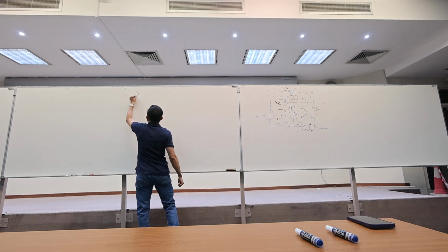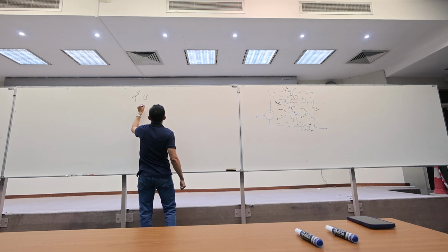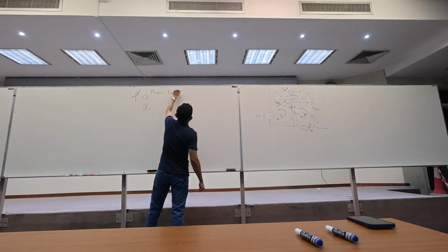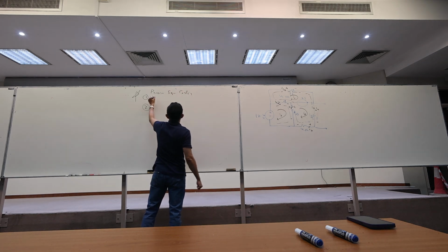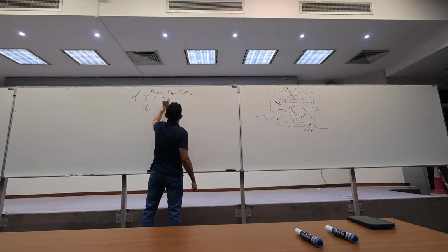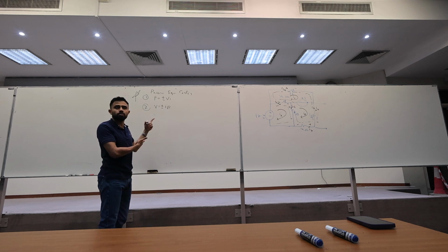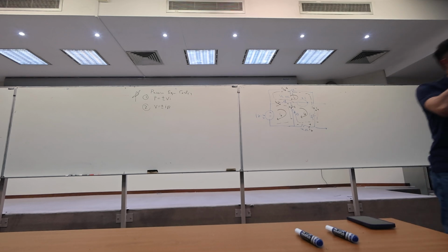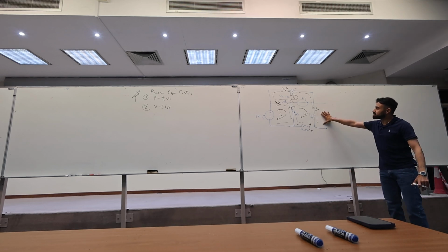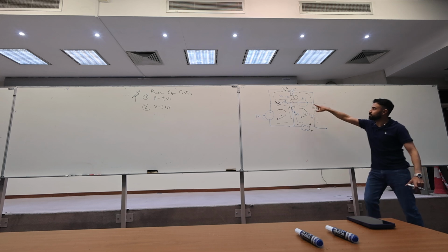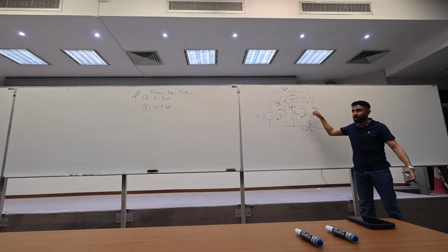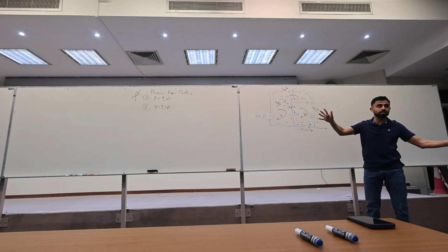So we come to the most important note that I need you to memorize. We have passive sign configuration. It comes as P equal plus or minus VI or V equal plus or minus IR. Today we included the capacitors, but it's not part of the test, okay? Now, how to set up these equations? It's a super mesh because we have a current source that we cannot know the voltage drop across it. So that's a very important concept.